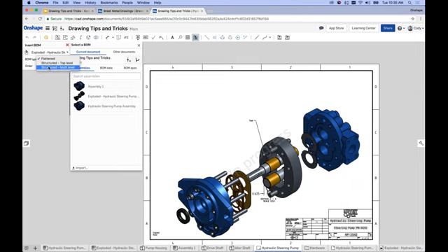Structured top level will give you a structured bill of materials with subassemblies, but it doesn't break down the parts within subassemblies. So subassemblies will be a single line item in the bill of material with no individual parts within it. And that's where structured multi-level comes in. This will give you the subassemblies and then the .1, .2, .3 nomenclature for parts within subassemblies. So I hope that's clear, but again, flattened, just simple list of parts. Top level gives you a view listing subassemblies as a single line item, and then the structured multi-level breaks down subassemblies and the parts within them, right?